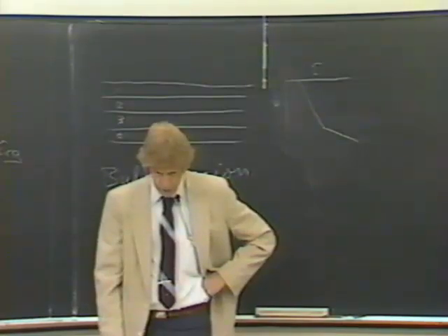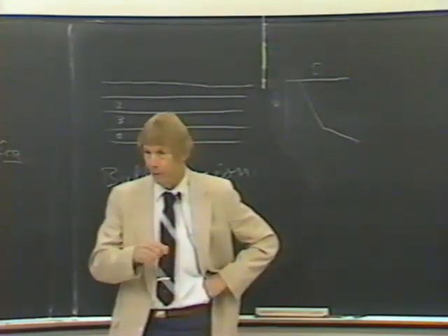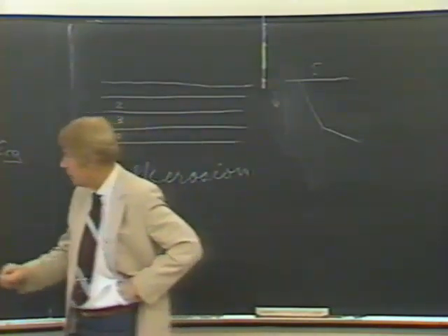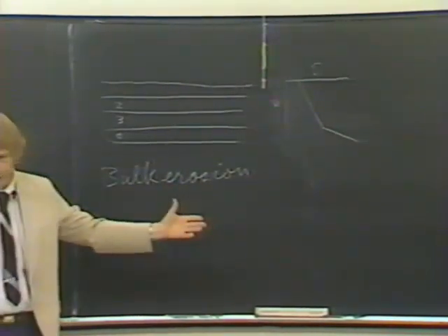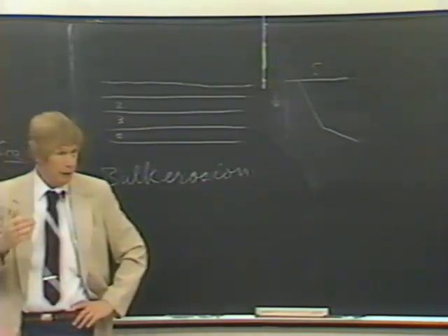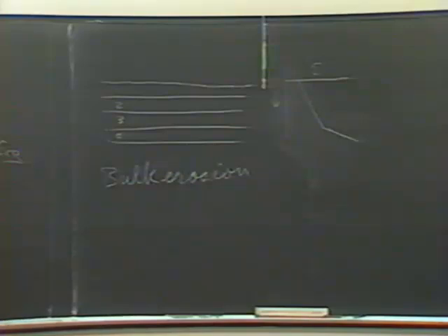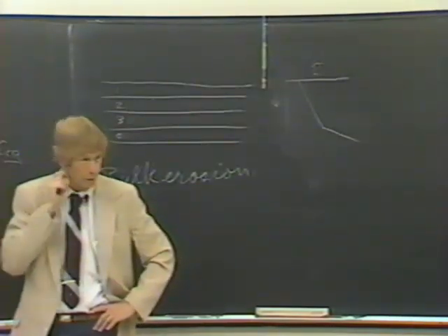And I think even people with a lot of experience will want to exercise the model that they develop enough so that they're confident that it is truly representing the system. The way you build that confidence is, as far as possible, get all of your inputs independent from your model. That is, minimize the number of things that you adjust to make the model fit the system. Get the settling velocities, if you can, independently, and of course, the currents, and the diffusion coefficients. Make sure they represent the salinities, and then compare the values that you get to similar models, if you can. You'll find that sometimes you get outrageous numbers. If you just try to make the model fit observed data, you get outrageous numbers. That's a warning that there's something wrong in the model. There's some uncertainty that's being included in your diffusion coefficient.